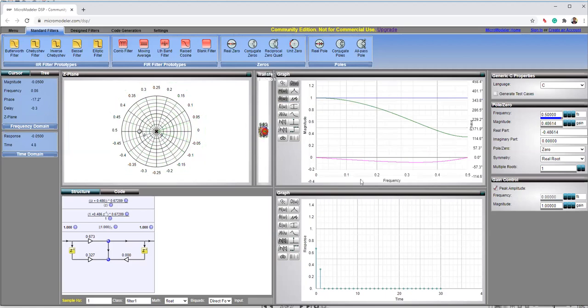This will give you the phase response. So this is the phase response. For an FIR filter, this is an FIR filter, you'll find linear phase response. Can you see that? If I block this, this is the phase response. Is that linear or non-linear? It's linear. If I change the pole location, can you see? It will be non-linear.